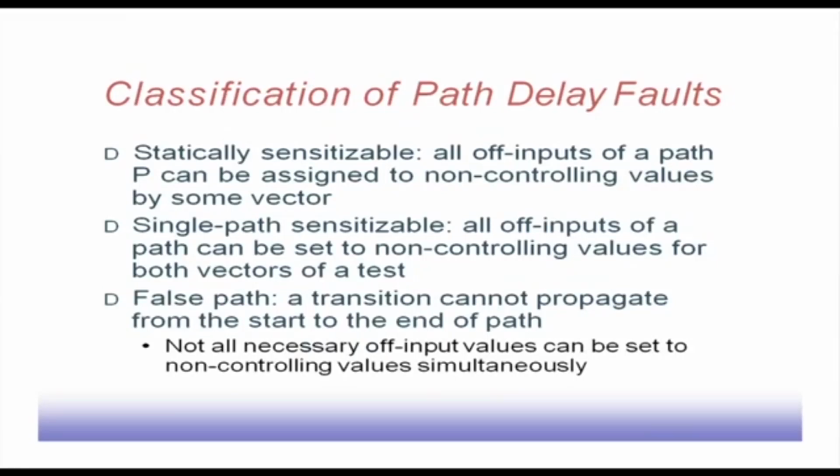Now these path delay faults can be classified into three categories. One is called statically sensitizable path, another is the single path sensitizable faults, another is a false path. So in the statically sensitizable case, all off inputs of a path P can be assigned non-controlling values by some vector.